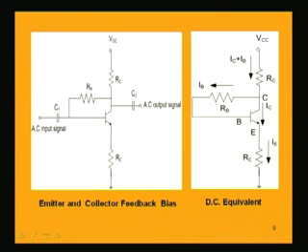Now, in order to analyze the circuit in the biasing condition, the equivalent DC circuit for this amplifier is this one, with C1 and C2 being open circuited under DC condition. So, we are getting this collector emitter feedback bias. Here there is this resistance in the emitter, others are the same as the scheme just now discussed, that is the collector feedback bias scheme.